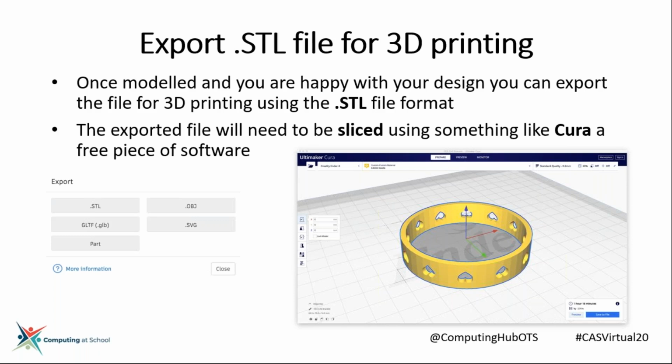So you can export them for 3D printing. If it's a 3D object, you can actually export files for cutting on a laser. But we're going to export this for 3D printing. So we just export in a .stl file. STL, standard tessellation language. It's a language that 3D printers understand. It converts it into G codes that drive the machine.